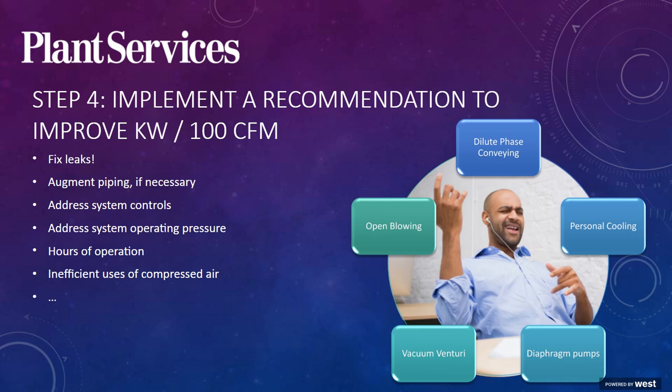Further, eliminating inefficient uses of compressed air is going to help you reduce the potential of about 50% of compressed air demands because it's wasted energy. Again, using engineered nozzles here, for example, to replace perforated pipe for blow-off applications, that's going to reduce your overall demand. These same uses could be an integral part of your plant operation, but they could be costing you a significant amount of money.